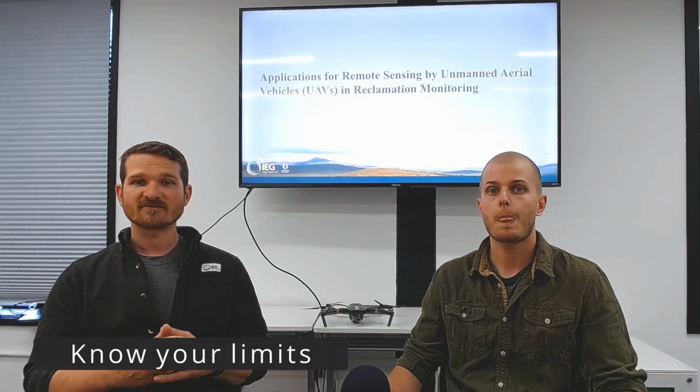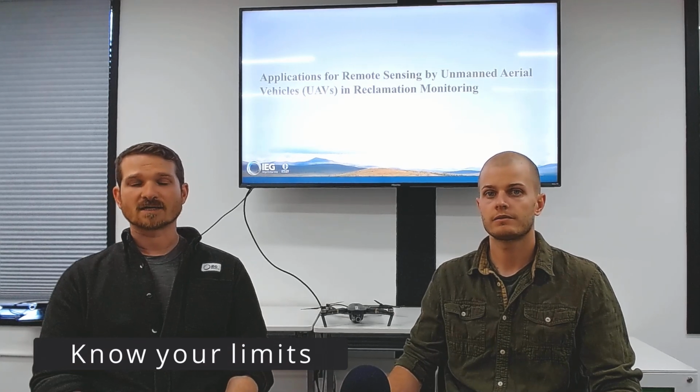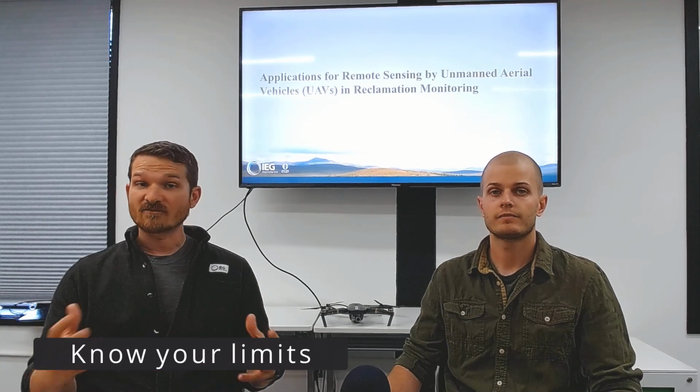Yeah, for sure. And building on that, the final tip is you've got to know your limits. It's really easy to get in over your head with a UAV remote sensing program. So you need to choose a flight platform that is suitable to the abilities of your pilots and sensors that have processing needs that fit the amount of post-processing that you're willing to commit to. And remember that everything will need to be ground truthed. So make sure that you have the skills and abilities to collect the needed data in order to do that.